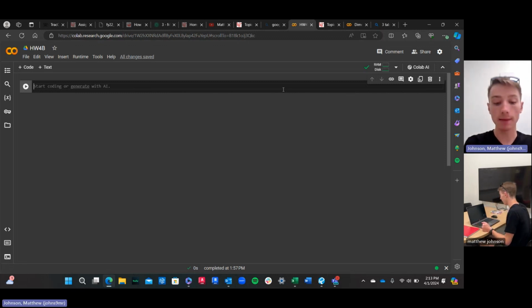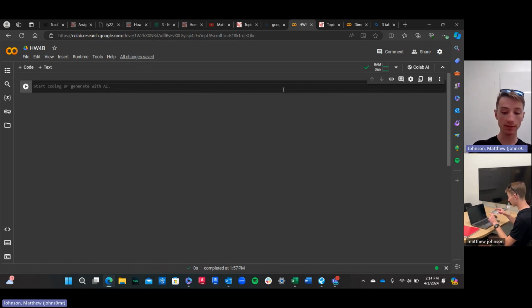Well, the Buckingham pi theorem tells us that the number of dimensionless groups that we can come up with from those variables is the rank of the matrix we just wrote down. Okay, and the matrix we just wrote down, remember, is the matrix of the powers of the units that go into the variables we're interested in.